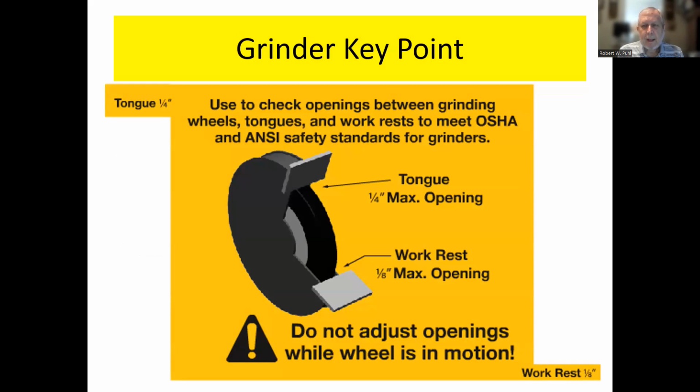Grinders. Yes, everybody has grinders in their shop. You might have one even at home. I suggest you find a picture like this or similar on the internet, laminate it and stick it up wherever you have a grinder so that nobody can say, I didn't know. Check openings between the grinding wheels, tongues, and work rests to meet OSHA and ANSI safety standards. The tongue at the top is a maximum of 1/4 inch from the wheel, and the work rest a maximum of 1/8 inch opening between it and the wheel. Now, as that wheel wears down, you've got to move those guards.